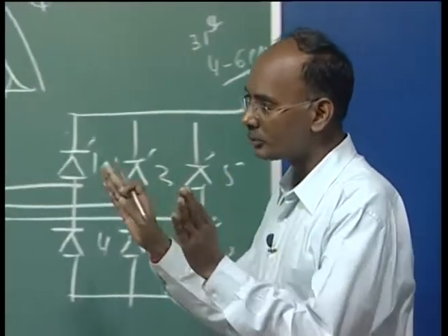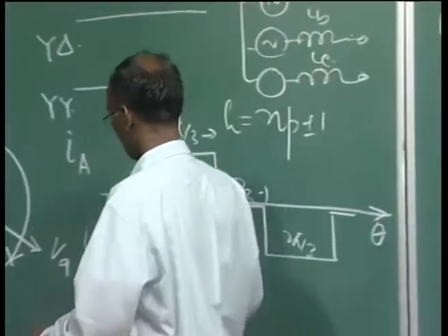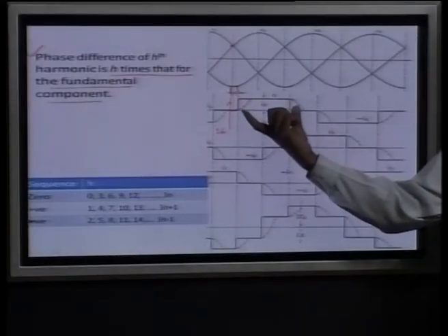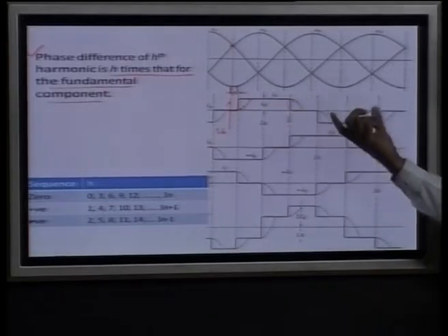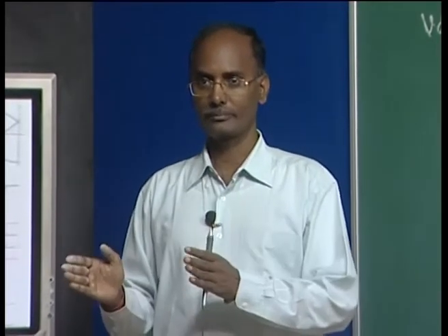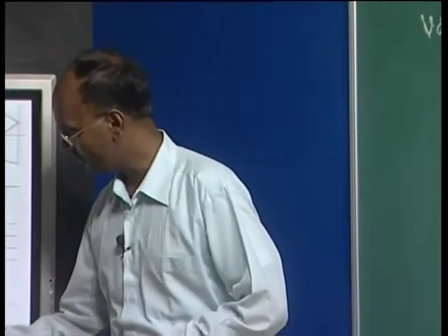To analyze first, do not consider the dotted line, just what I showed here. You can see we get this 120 degree positive pulse, then a 60 degree zero current, and then a negative 120 degree pulse. This is the case when we have a star-star connection of the transformer. If you have star-delta, then the line current on that side is going to have this much.